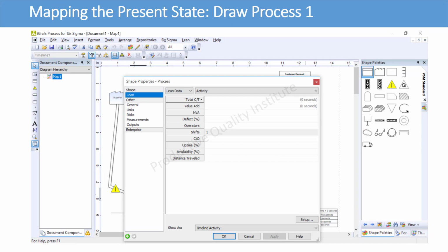For the shape properties data, some shape data elements are entered, some are calculated, and some entered data elements are calculated by relationship to other data elements. For example, if you enter processing time, it is assumed to be all value-add time. However, if you also enter non-value-added time, value-add time will be calculated for you. If certain data elements, such as NVA or VA, total greater than the total cycle time, a data entry warning appears to alert you to the discrepancy. The value in parentheses shows the correct or implied value.